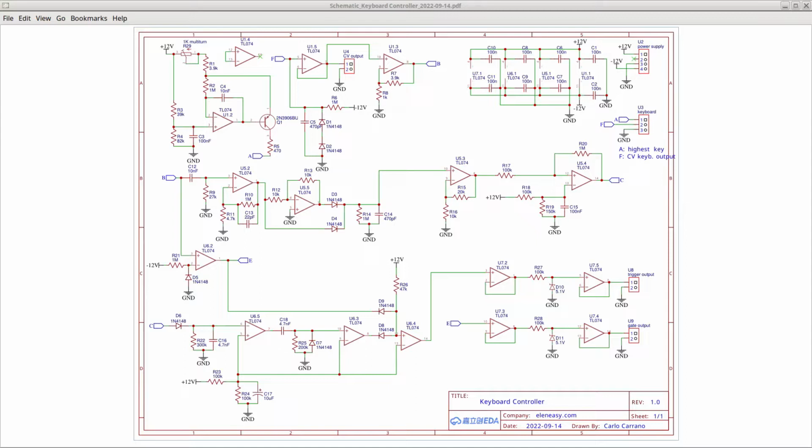The current generator provides a constant current at the collector of Q1, which is a PNP transistor. I use a PNP transistor to polarize the resistors with the positive and the negative side in the right place. It works the same as the generator demoed in my previous video on current generators, but it is just using a polarization that is just the opposite.